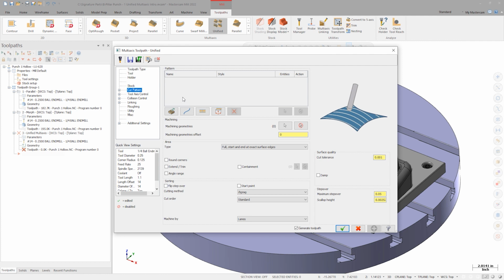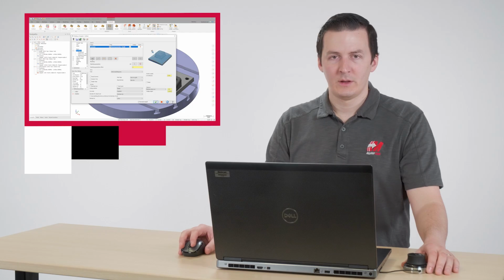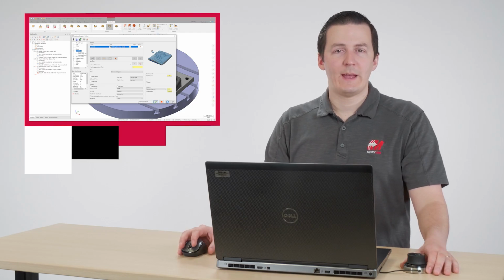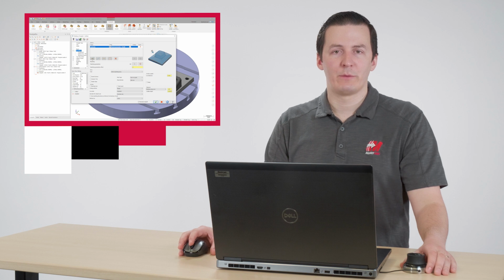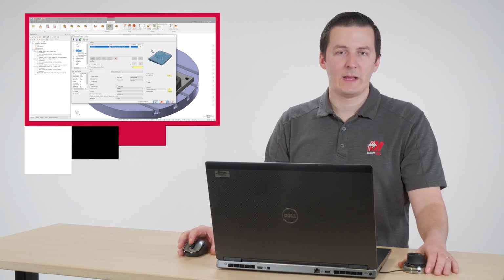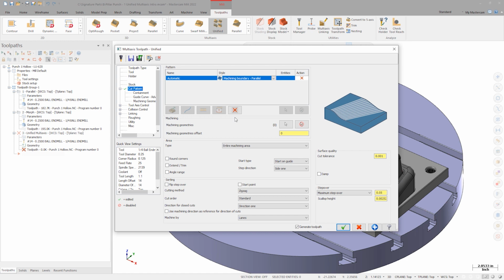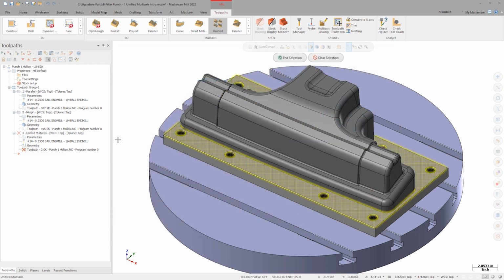If we shift our focus to the Pattern Definition area of the page, we can see the source of this toolpath's flexibility. The Unified Toolpath allows 4 different input types to define the cut pattern. From left to right, they are automatic, curve, surface, and plane. Let's explore automatic mode, which is the new cut pattern type offered by the Unified Toolpath. Automatic mode doesn't require any specific entities to be selected to define the cut pattern. Instead, it uses the boundary of the selected machining geometry to create motion similar to that of the equal scallop toolpath. Let's select Automatic and enter Machining Geometry Selection.